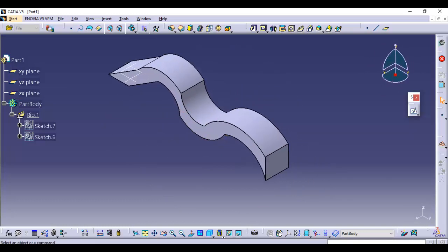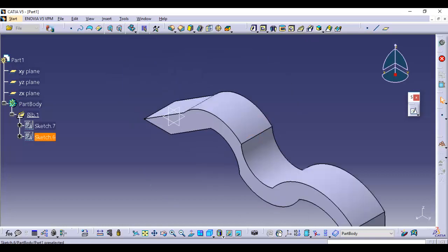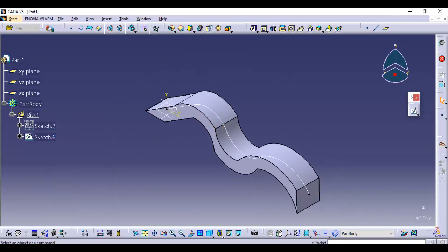This gives you freedom of creating a solid along a guide curve or center curve, you can say. Then the next command is the slot command, and this is exactly reverse or opposite of the rib command. We will use the same center curve but a different section.